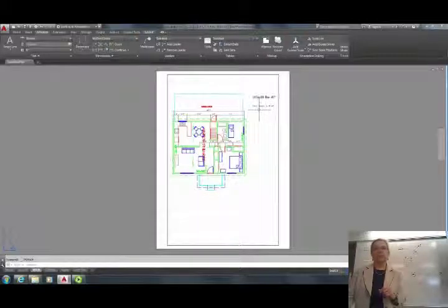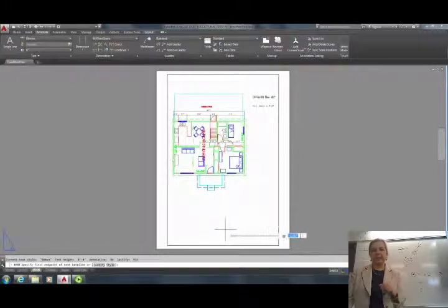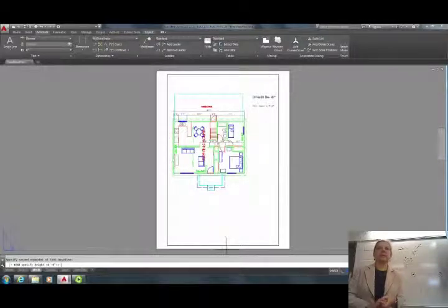So what do I do now, ladies and gentlemen? What is my height now in paper space? Anybody? It remembers 6 inch. But what do I need now? I'm in paper space, and I want 1/16 of an inch.